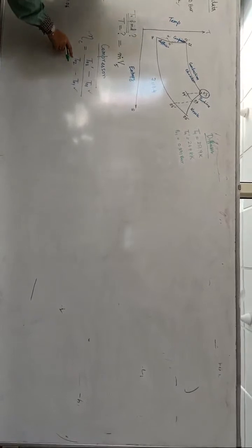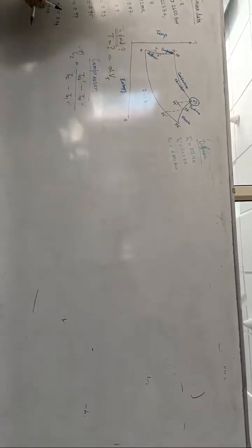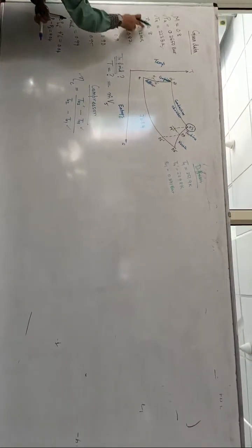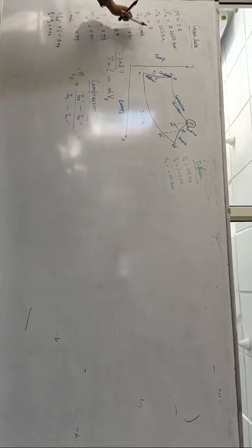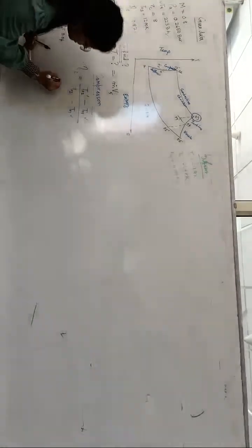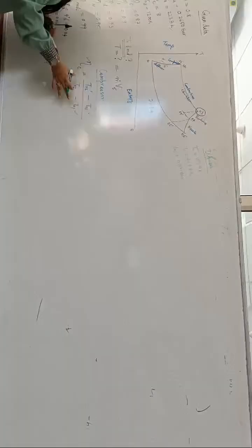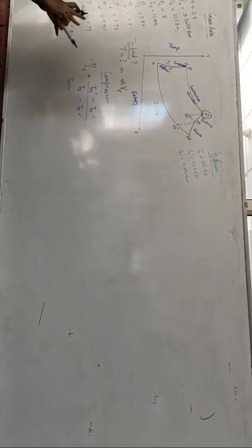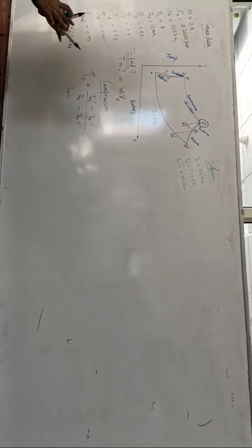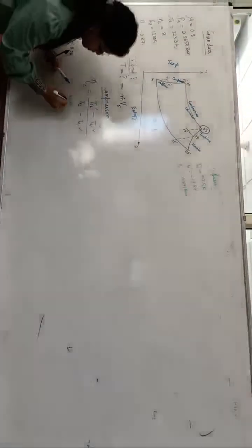Now, again here the issue is T02 and T02 prime. But here for the compressor they have given the pressure ratio. That is, RC is the given pressure ratio. So before substitution, first simplify it, because once you substitute the value, it's going to be more complicated. First you simplify and then you substitute.